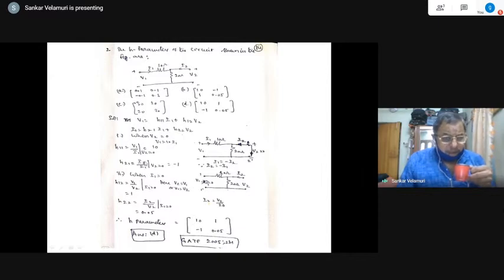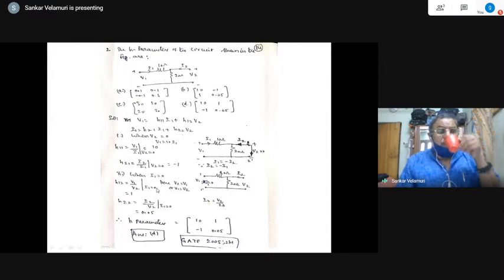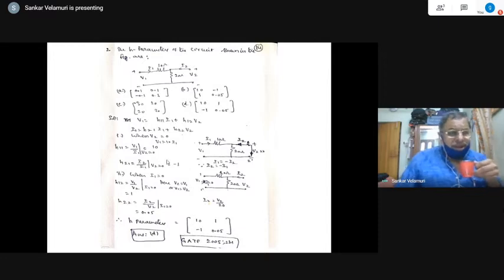So you can see clearly from this, the magnitude of that one is the same with a minus sign, because this is the current ratio with port 2 short circuited. This is the voltage ratio with port 1 open circuit. Both are different parameters, but the ratios are the same because of the reciprocal network. Just as the ratio of the excitation to the response was shown earlier, using the reciprocity theorem, that is applicable.